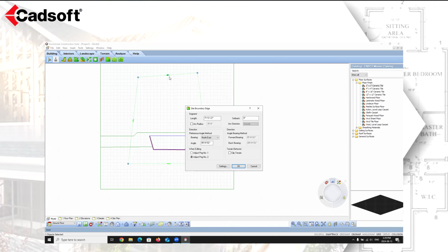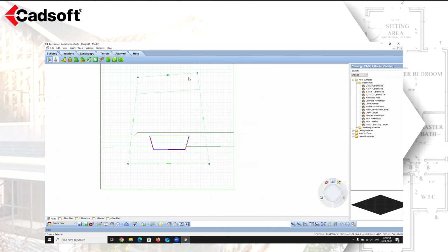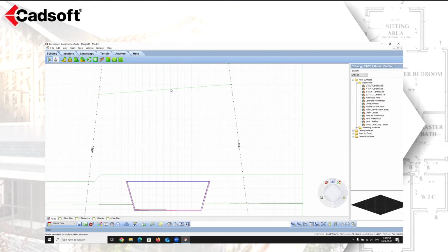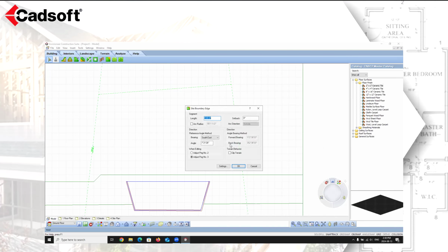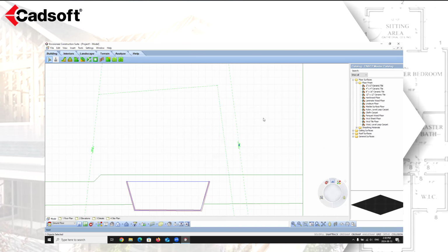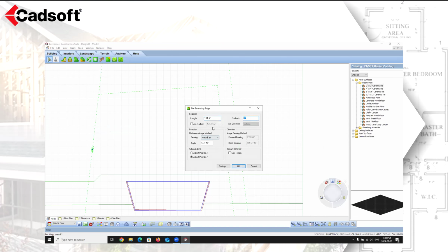Whatever edge is selected, you can say from the front edge of my property, I need at least, let's just say 20 feet. So that's going to change that to be a 20-foot setback. When I select this edge, I can go into its properties and I can say from each edge, I only need to have an 8-foot setback. So from that edge, it's going to be 8 foot. From this edge, it's going to be 8 foot as well.